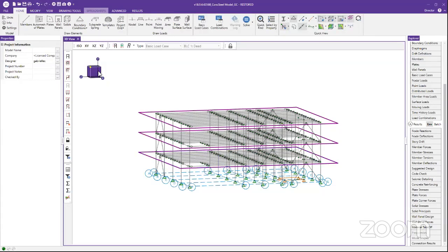The other way to do it, you could do something like a semi-rigid diaphragm, which would mean you'd have plates on top of that. Now, RISA Floor will also do a semi-rigid diaphragm, a flexible diaphragm, or rigid. When you're in RISA-3D on its own, it's just going to be doing the rigid diaphragm. So you've got the rigid diaphragm where you can distribute that load on that level, and that's how we are going to assume it's applied to the structure.